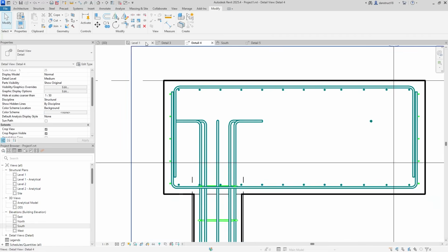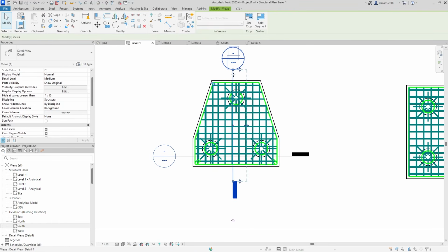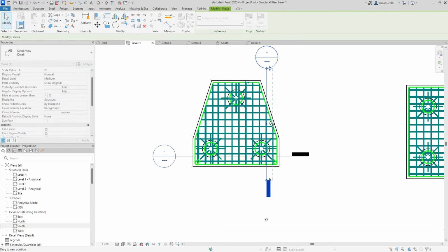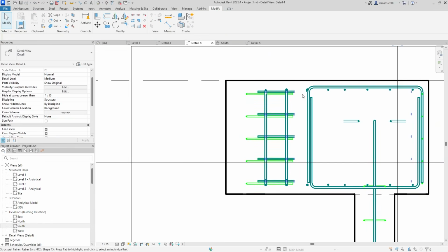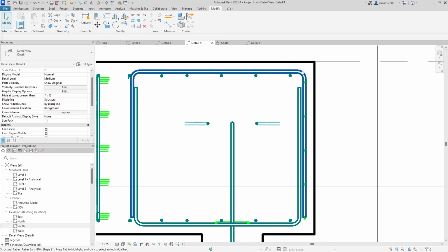All right, good. So come back here into level 1, then click here and move in this direction and just drag the far clip offset to this point here. Then go ahead and open it up, and we want to check for this side here.